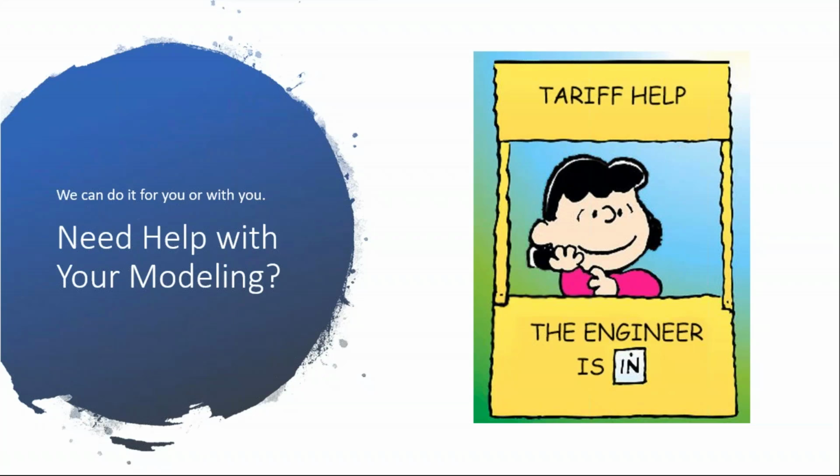Are there general design rules for which distributed generation best fits? Well, there are rules of thumb, but I always get nervous about rules of thumb, because that's one of the reasons we created the software. We realized the rules of thumb aren't really good enough most of the time. Having said that, I will give you a generalization: load following tends to be better for systems with higher renewable penetration, and cycle charging tends to be better for systems with lower renewable penetration. But that's just a generalization, and it's definitely not always true.